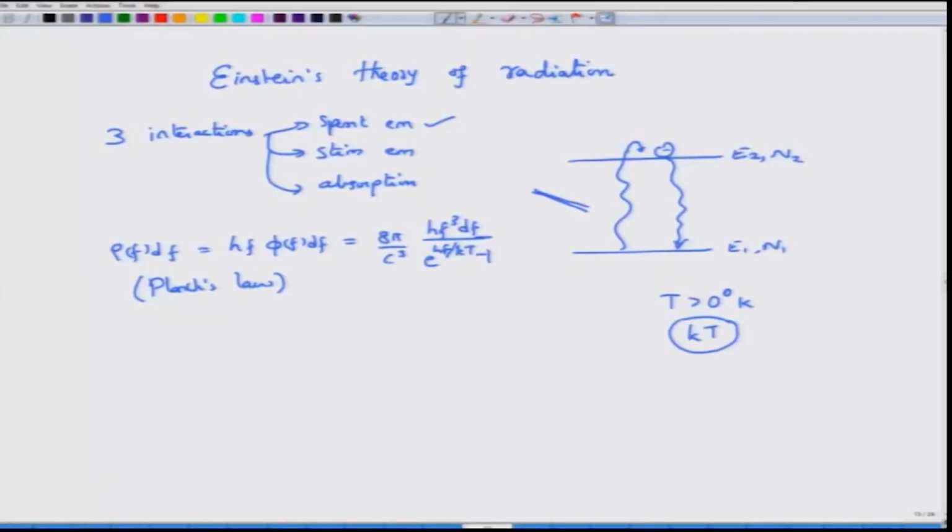and then jumping up to the next energy level. But it is possible to excite atoms in a much more controlled way by having an external pump signal. Having an external pump signal allows these atoms in the ground state to absorb the energy coming from an external energy source, which we call the pump, which is typically an optical signal or photons, or it could be simple current. Both types are used in fiber optic communication systems to make different kinds of lasers. The one that is optically pumped is the erbium doped fiber, and you make a laser out of it. We call this an erbium doped fiber laser.